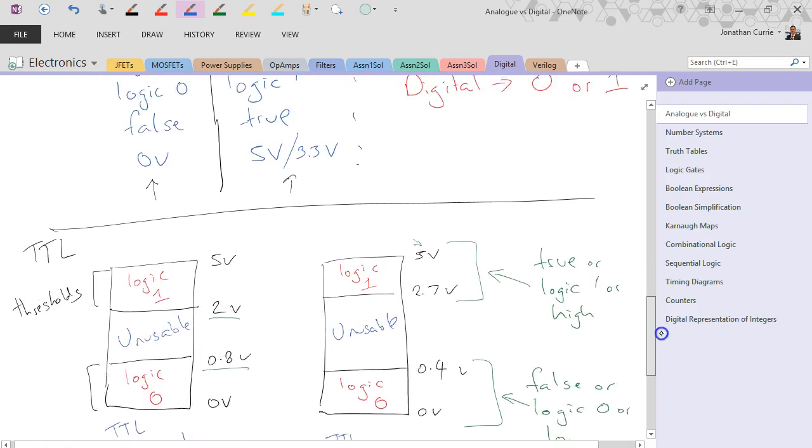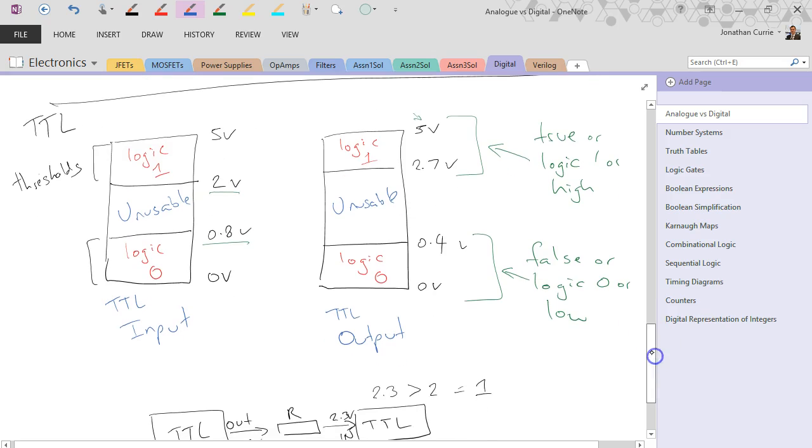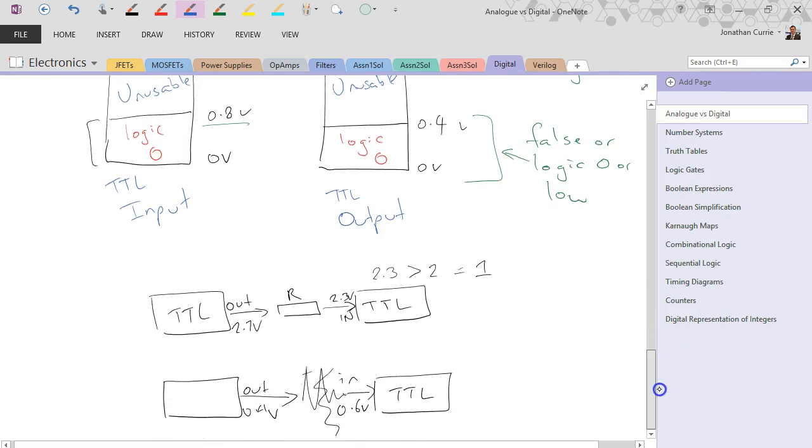off position. And noting that there is a tolerance around that. So a logic 1 would fit into, let's say, the output of 3.3 volts. Okay, or a logic 1 would also fall into the input of 2.5 volts, if we're looking at it from an input point of view. So different ways you can look at the same signal, just giving a little bit of operational tolerance.